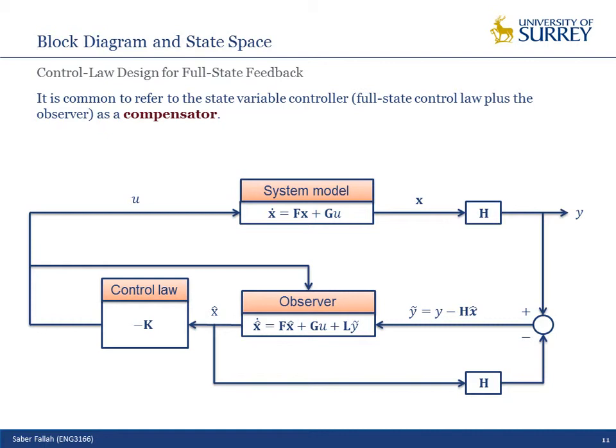Or you can use the state of the system Zs, Z dot S, Zu, Z dot U. In reality, if you use Zs, Zu, Z dot S, Z dot U, none of them are measurable because they are absolute. What you can do is use two accelerometers, one on the chassis corner, the sprung mass, and one on the tire, the wheel hub. Based on the acceleration of these two, estimate the other states of your system.